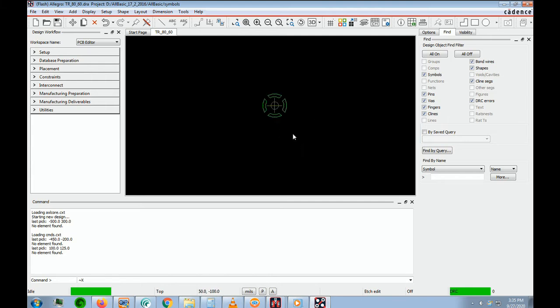If we zoom in a little more, we see that the inner diameter is 60, the outer is 80, and the spokes are 15. Of course, as you know, this is because we do not want this to act as a heat sink.